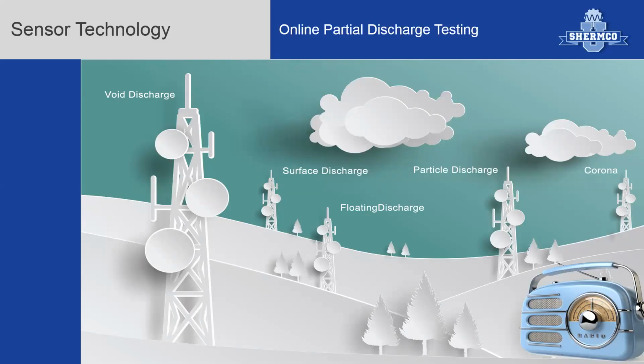All right, let's talk a little bit about sensor technology. In the image here, I refer to the partial discharge receiver, or partial discharge detection test set, as kind of being a radio, and the partial discharge sensors as being different antennas designed to pick up different frequency bands. Again, in the online world of partial discharge, the energy is emitted in the form of different frequency bands and electromagnetic waves. So depending upon where the partial discharge is or the type of partial discharge, the various sensors, in a very simple analogy, can be referred to as different antennas picking up the events. And the partial discharge test set can be very simplistically referred to as the radio picking up these different frequency bands.